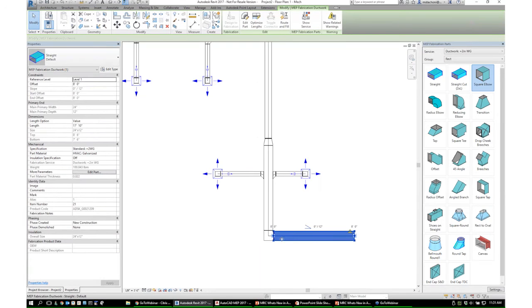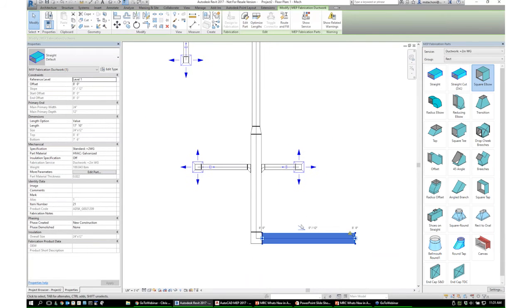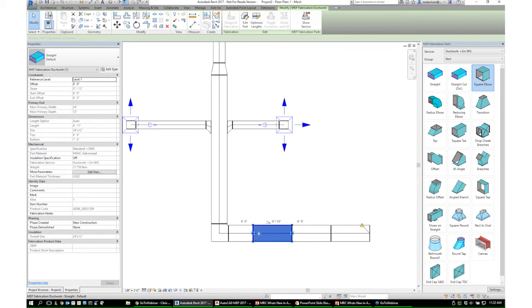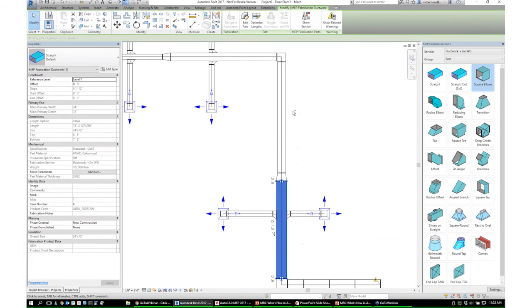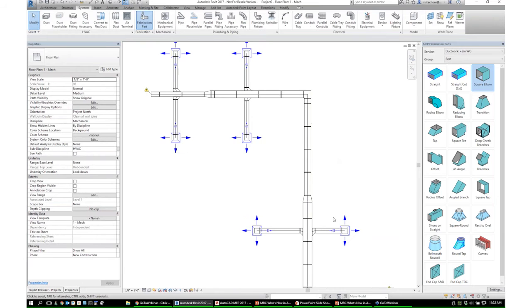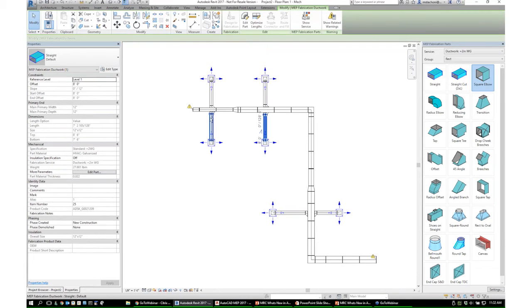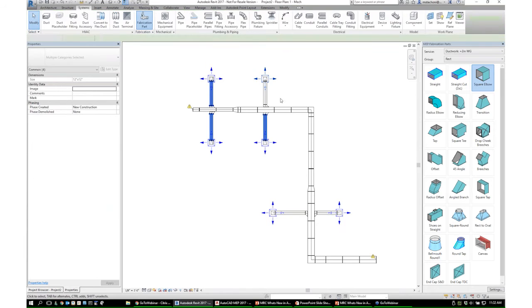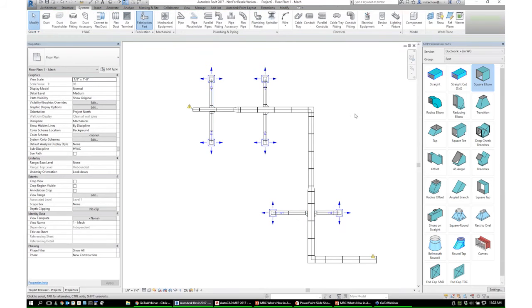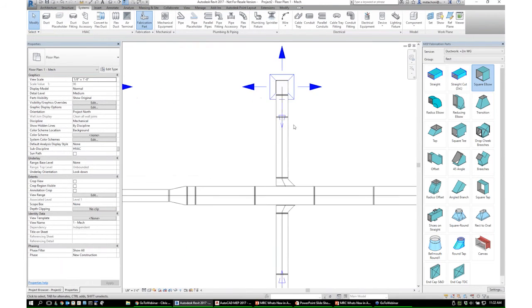Now I have lengths here that are obviously longer than the length we need for this particular kind of ductwork. This is longer than 5'11", obviously, but if I hit optimize lengths, you'll see it puts in the 4'11" duct, and where it has to put a smaller one in, it puts the smaller one in there. So I can select these segments here, hit optimize lengths, and it does this. I can do the same thing for these branches as well. Makes that fairly simple.